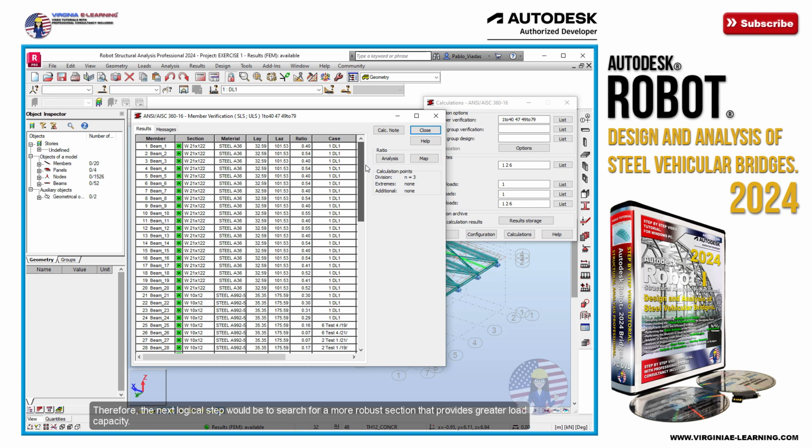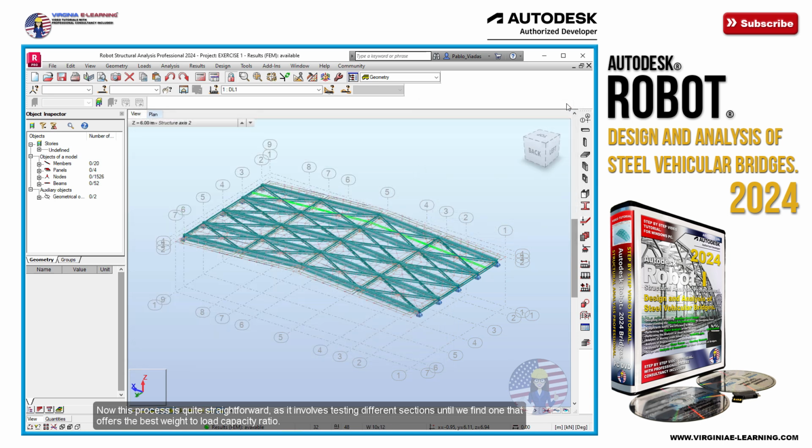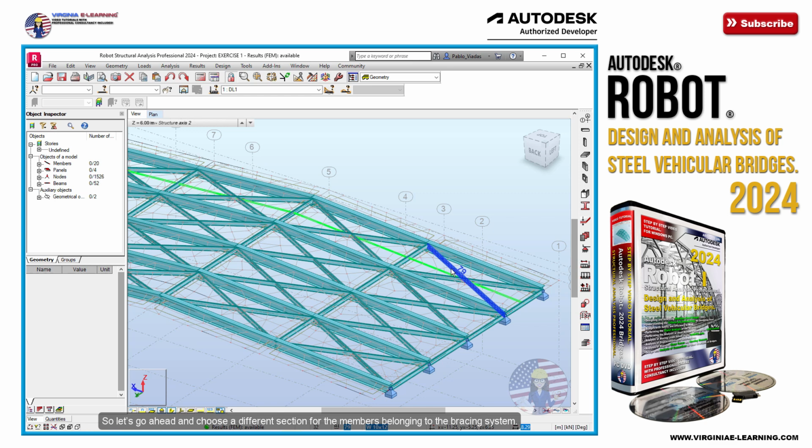Therefore, the next logical step would be to search for a more robust section that provides greater load capacity. Now this process is quite straightforward, as it involves testing different sections until we find one that offers the best weight to load capacity ratio. So let's go ahead and choose a different section for the members belonging to the bracing system.